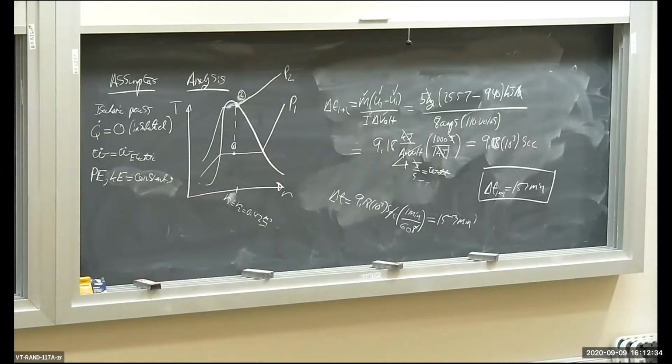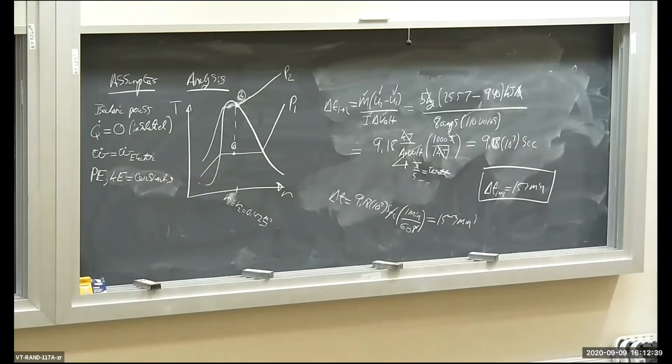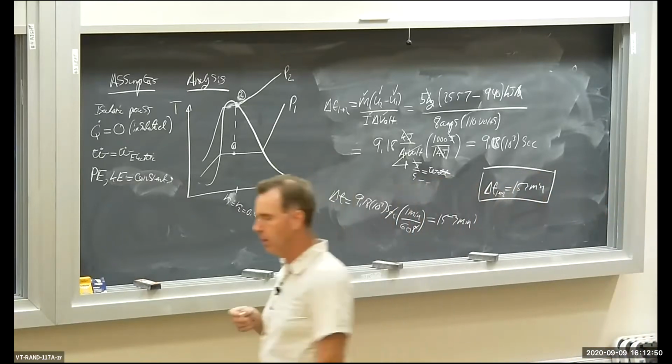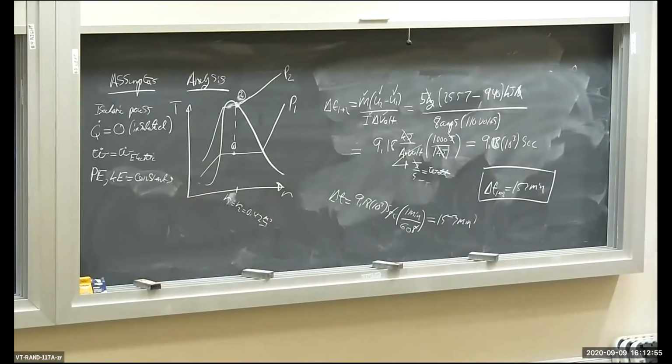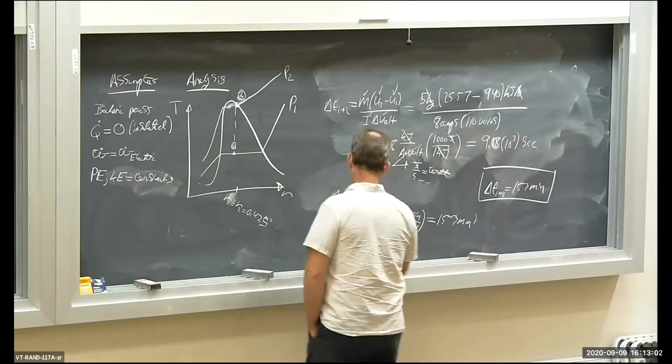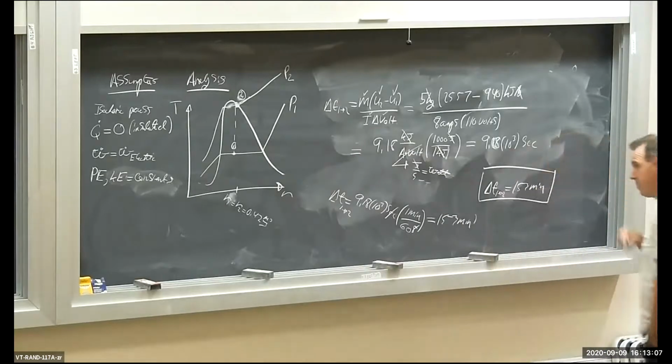This is kind of an interesting problem in the sense that we had a two-phase mixture to deal with, not an ideal gas, so that complicated things a little bit. We had a quality to worry about and used the saturation tables. We also had time in this problem, so I used the rate-based energy equation and then integrated it over the process to extract delta T, which is what I was looking for. I was calling this delta T from 1 to 2.